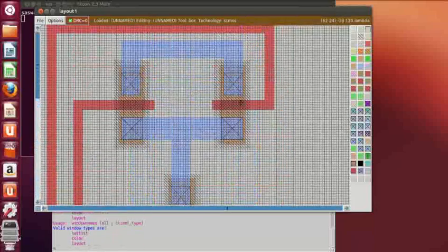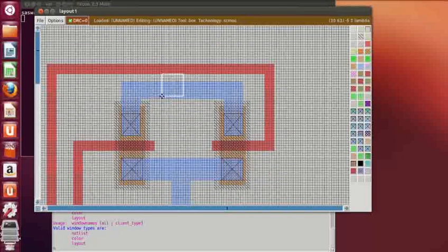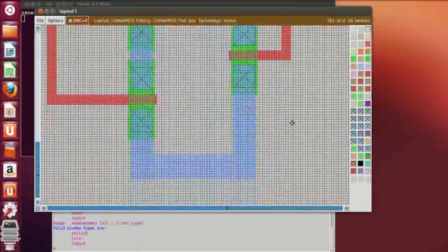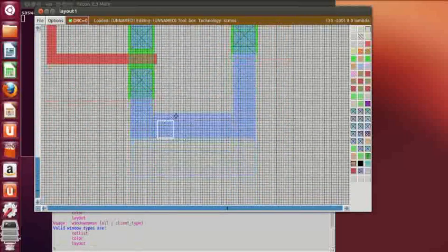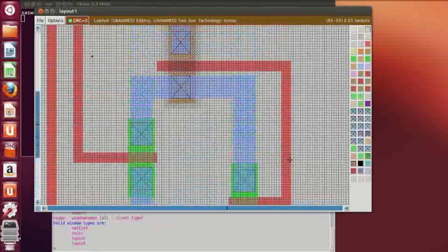now this is the VDD, so you have to place some contacts over here also. So select the area, middle click on N substrate contact. Similarly over here, you have the P substrate contact. After placing these contacts,